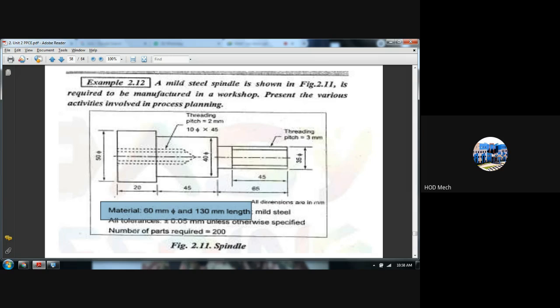And the second statement talks about the tolerances you can give to the dimensions wherever applicable, unless otherwise specifically stated. So nowhere else is it specifically stated. If you look at all the dimensions in the dimension diagram, no specific tolerance is specified. Therefore, the tolerance that is allowed is plus or minus 0.05 mm.